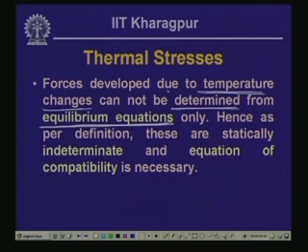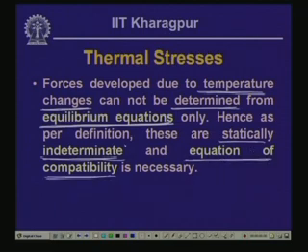For the systems for which we can evaluate the internal forces based on the equations of equilibrium, we call those systems determinate. But if we cannot evaluate the forces which are getting developed due to change in the temperature from the equilibrium equations, then we call these systems indeterminate. Hence, this kind of thermal stresses induced in the member are basically statically indeterminate, and we need to use the equation of compatibility for the solution of these forces, for evaluating the internal forces.